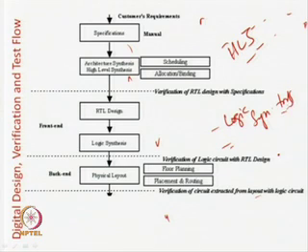This part I think many of you have already learned, like Karnaugh map and Quine-McCluskey. They basically take your design, like a counter or adder, and generate the gate level design. Karnaugh map and Quine-McCluskey can work up to 10 variables or 20 variables, but in VLSI we have 100 variables or even 1000 variables. So, how can you do a Karnaugh map type optimization for 1000 variables? You require different types of CAD tools for that. That we will be learning in the second phase.